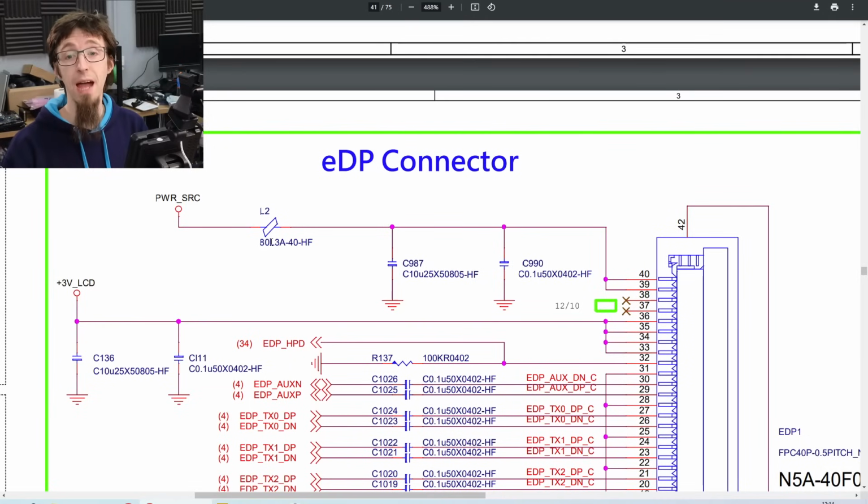This is often seen at power inputs, just as a method of smoothing out the incoming power a bit, so if the load suddenly takes an enormous gulp of current, there is that bit of buffer in the inductor to release some energy. And if suddenly the load bangs from 0 to 100, it stops that shock from going up the power line and possibly damaging and upsetting things further up the chain.